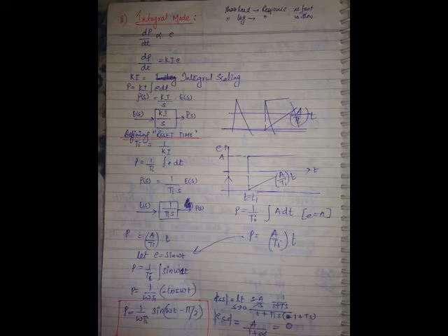Sudden error means suddenly if the inlet changes, the water level suddenly jumps to a new value. If a sudden error occurs, what is the output of the derivative controller? 0, which means it is not responding. Is this an advantage or a disadvantage? This is the disadvantage of a derivative controller. It cannot respond to sudden errors. If it is unable to respond to sudden errors, then let us see how it responds to a ramp error, At.